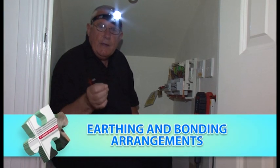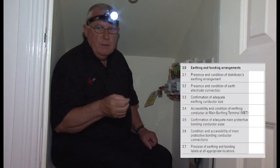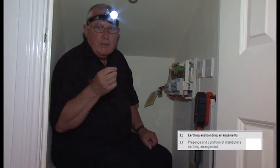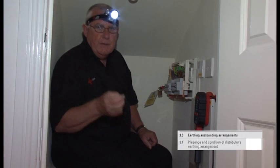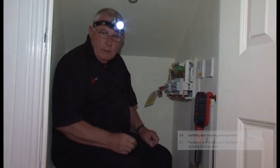Next, we need to check the earthing and bonding arrangements. First, the earthing arrangement. Well, the good news is that we've seen the earthing conductor connected between the supply at the intake and the MET, and it's in good condition. However, to actually verify that this installation does have an earth will require an electrical test that I'll do later, so I won't tick that box just yet. There's no earth electrode in this installation, so that will be NA, not applicable.